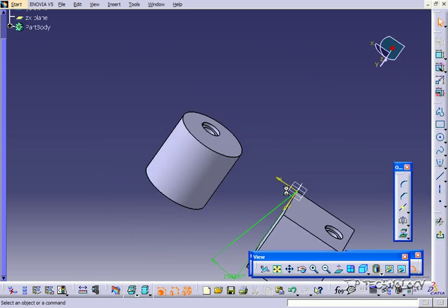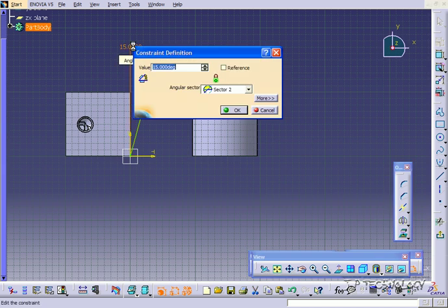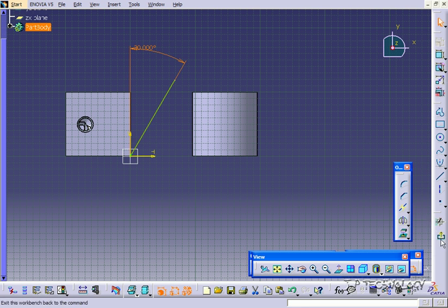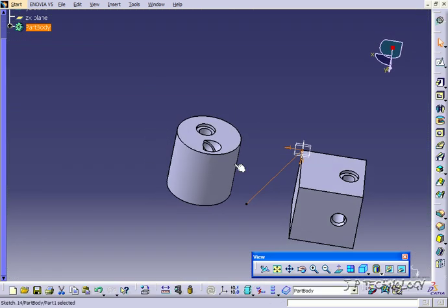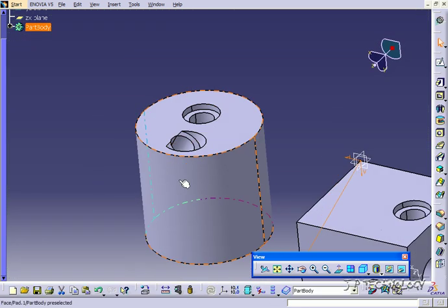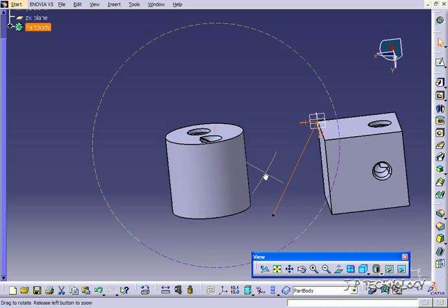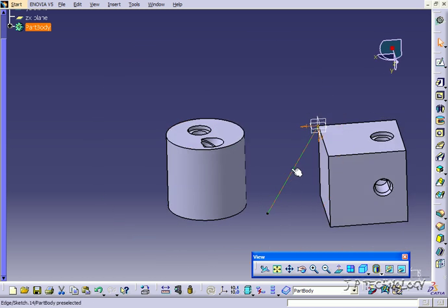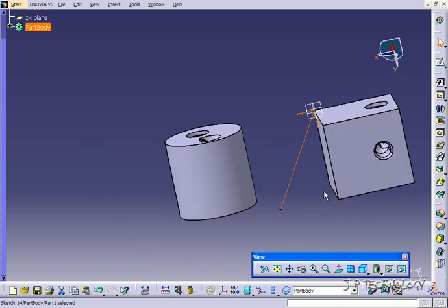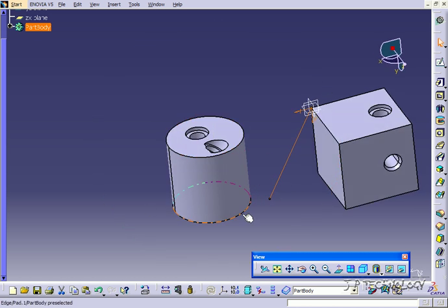Now if we double click on this line and say we change this to 30 degrees, then everything's going to automatically change. So let's go and update it, and now it's on a 30-degree angle. So when you're making the hole, you're able to either align it with a sketch line or an edge. So say that there was actually a solid here that was along that line, you're able to actually select that line too, and it's going to follow that line.